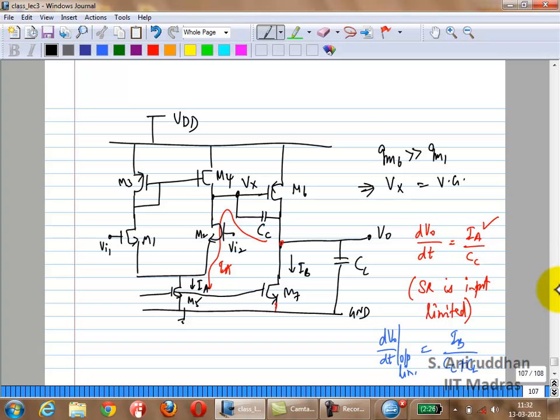I give you the answer now, but I want you to go back and try to calculate it for 60 degrees. In class we saw what happens if you have 45 degrees: you want the second pole to be right on omega u. If you want 60 degrees, it will be a new calculation.